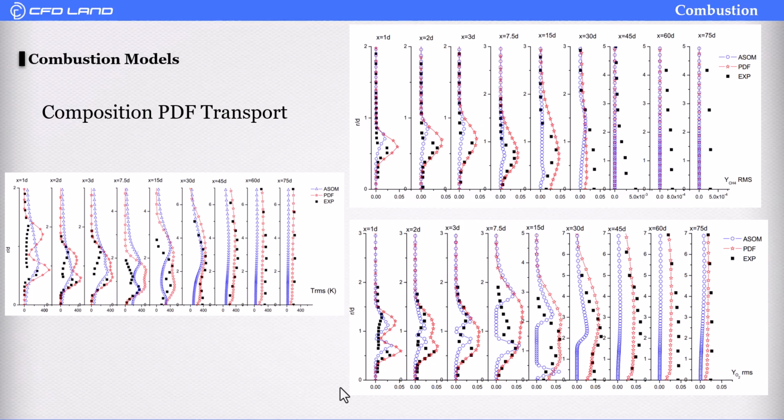With an appropriate chemical mechanism, kinetically controlled species such as CO, carbon monoxide, and nitrogen oxides, as well as flame extinction and ignition, can be predicted. This method is computationally expensive, and it is better to start with a small grid, preferably in 2 dimensions.